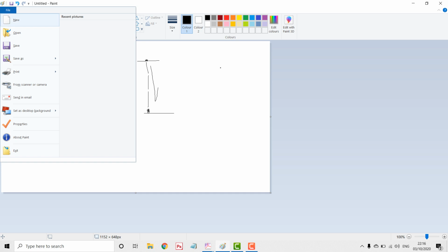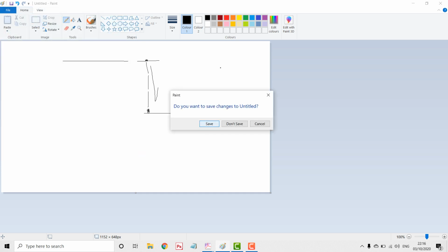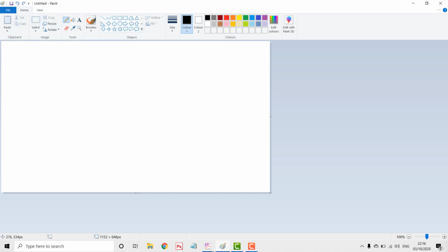Suppose you have a skin panel which is something like this, of certain thickness, and when this geometry is imported into the pre-processor, what you have to do is extract the mid surface, and then mesh the geometry.